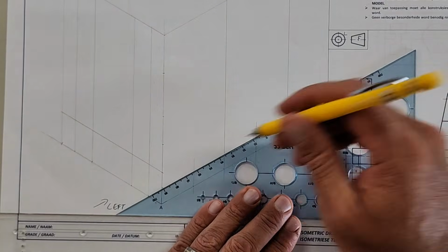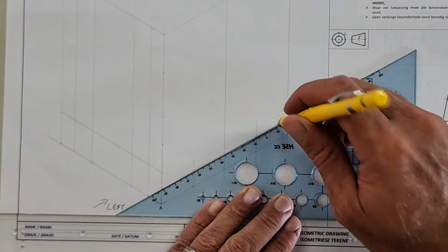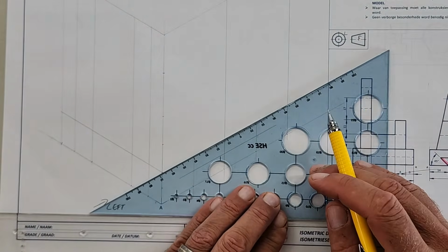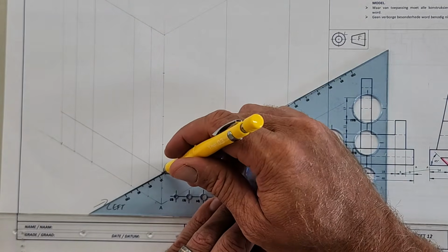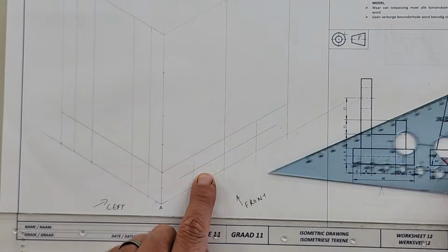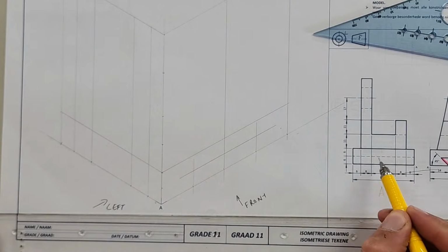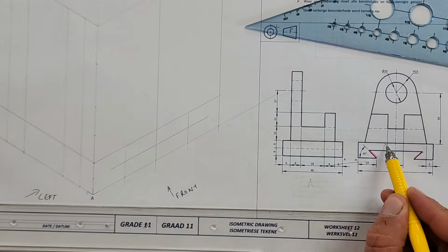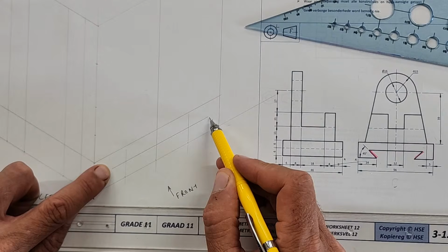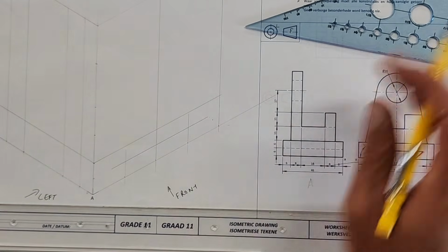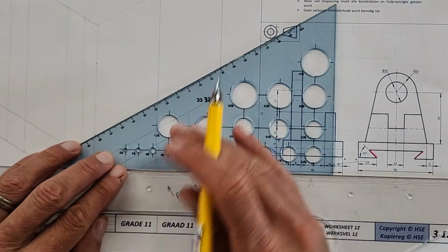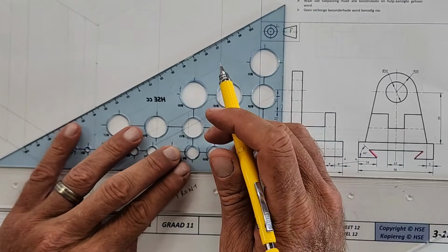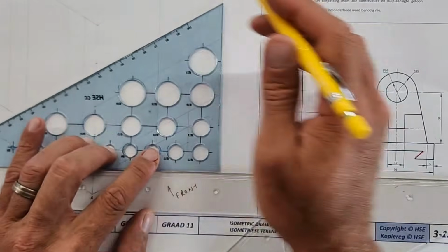So you see here, I'm also judging which lines I need to draw now. I don't need to draw on the side there, and that is to help me with less confusion. If you look at this left view, there are no corners here, so I left that one open, but on the front there are actually 2 heights, and so I've drawn that in also where I'm expecting it to be. Then there's another height that comes across here. Let's do them on the front. We'll project backward.